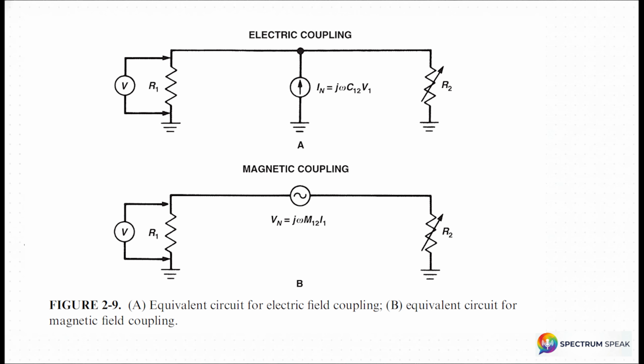If the noise voltage decreases, you're dealing with an electric field because you're literally shorting out a parallel current source. But if the noise voltage increases, boom, your pickup is magnetic. Why? Because you are drawing more current from a series voltage source. It's such a clever test.